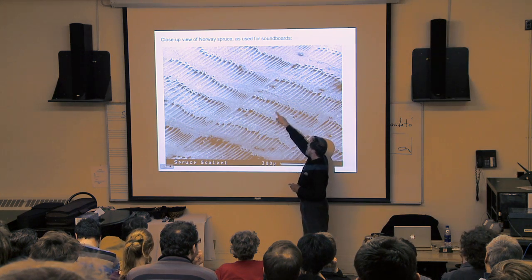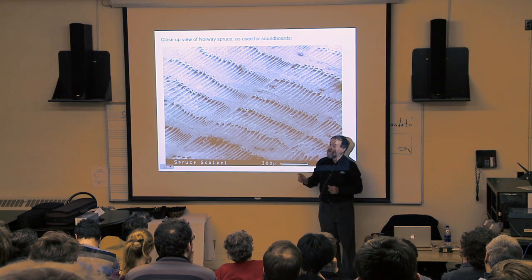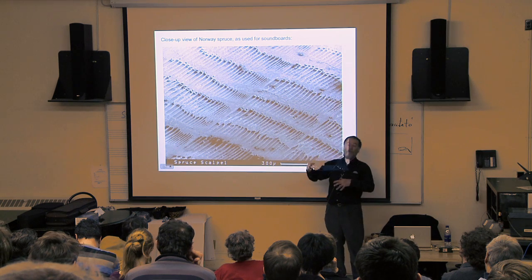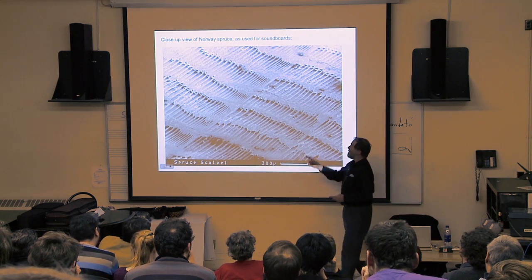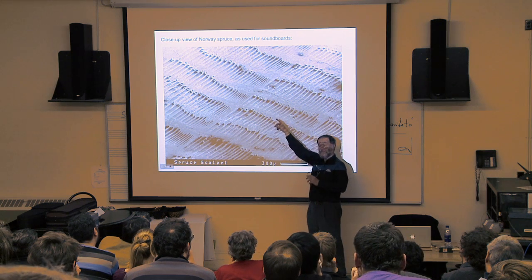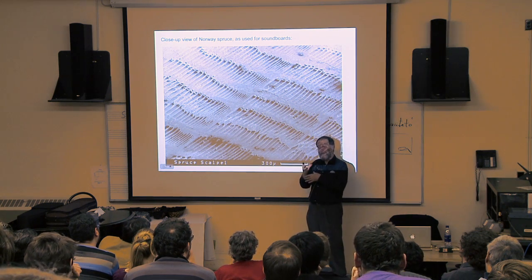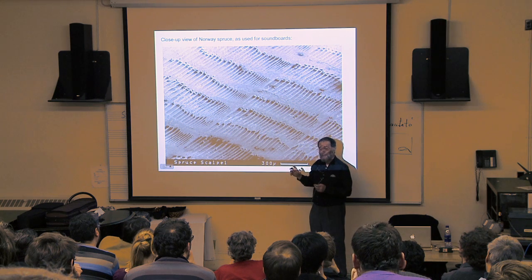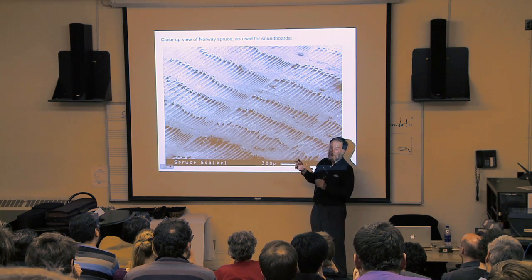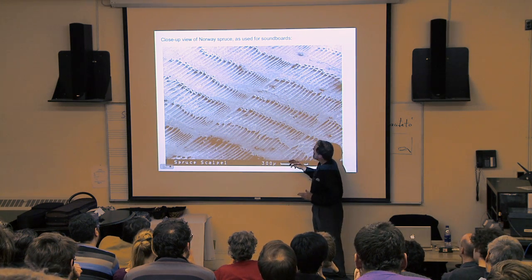Lots of space down all these tunnels here. And that's a very efficient way, because wood is made of a polymer, which is not so different from those other polymers that were on the diagram, but because it's been structured with this microstructure with a lot of empty space, this is just a really good way of getting high stiffness to weight ratios in the particular combination that you need for this loudness.